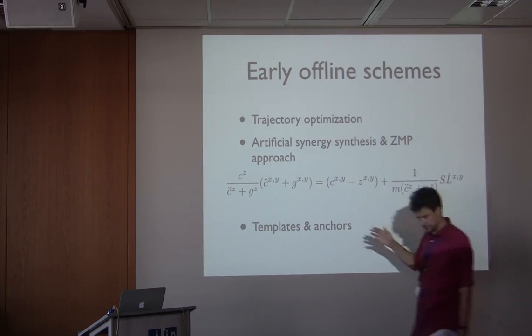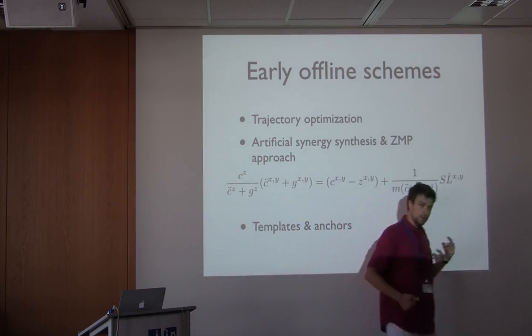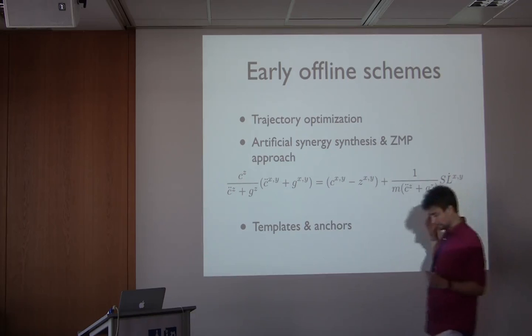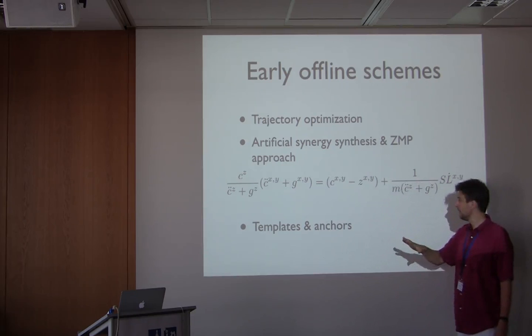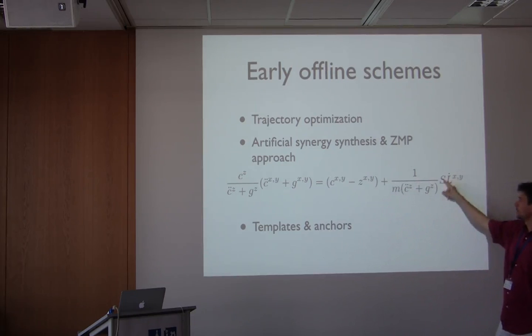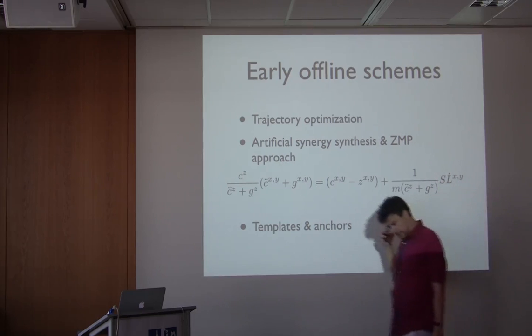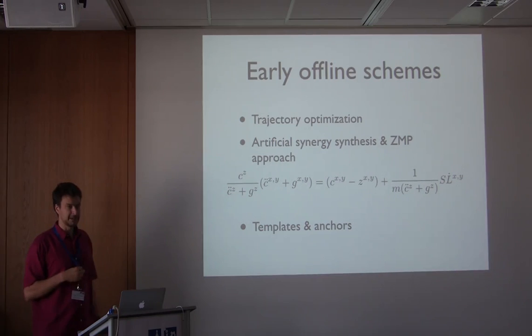So his original idea in the 70s was to say, well, let's use pre-recorded walking motions. And then you just use the arms to keep your equilibrium. So what he was using is in fact predefining the whole joint motion of the system, except for 2 degrees of freedom, which would modify the angular momentum of your system. So it was a purely theoretical idea in the 70s, but it was realized at the end of the 80s in the Waseda University that I mentioned.